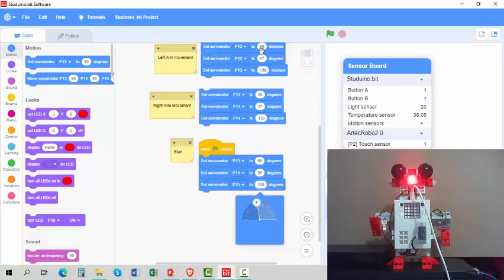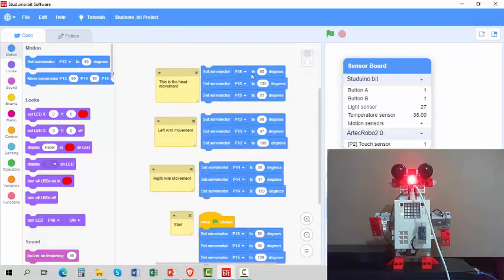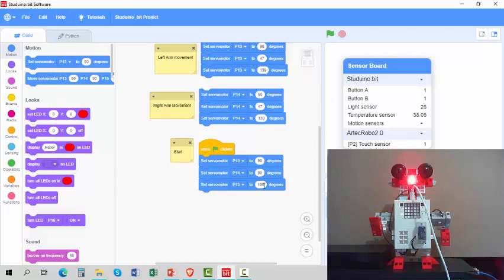No, I don't want to. My servo was 98, so I want mine at 98. That's where I want mine. And the other two are set to 90 and 90. Those servos, that's center position. If you look at the robot, I just set it back and everything is in resting position. Right, that's the first thing.